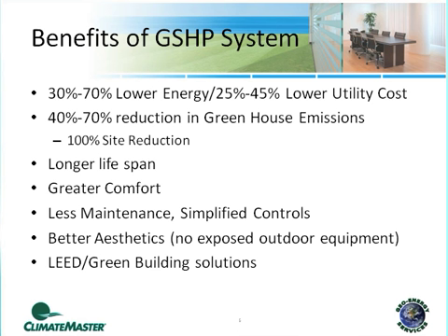Now, as far as the general understanding of ground source heat pump systems, if you're unaware of some of the key benefits, you can see them on the slide here. The first thing to note is the energy savings component. That's a big reason why our industry is in existence. If you look at a typical building project, and understand that we're trying to generically cover a lot of projects across the United States, when you look at these projects as a whole, a typical project will save somewhere between 30 to 70% lower energy costs, which typically translates to about 25 to 45% lower utility costs. Now, again, things that are going to vary are the actual utility rates in your area, things like natural gas prices, propane prices, heating oil prices, and electricity prices.